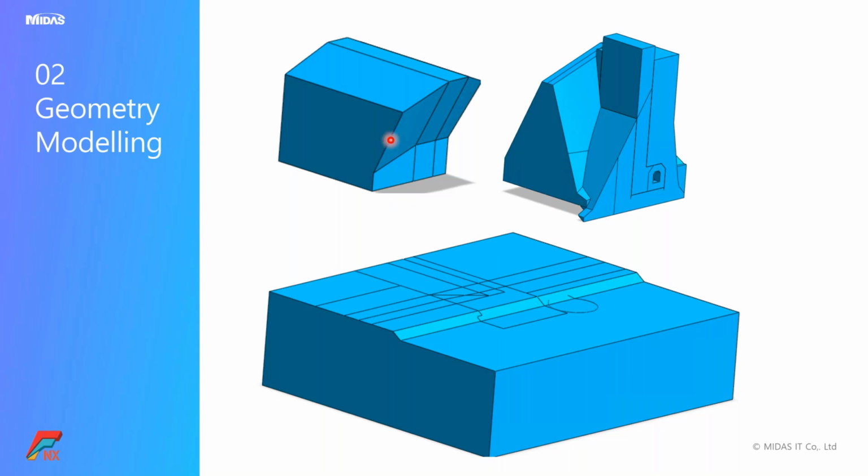Due to this, there will be some additional force applied by the backfill onto the abutment. Hence, we want to consider the backfill as a direct model rather than applying it as a mass or a load onto the abutment. So the idea is to consider the effect of backfill and how it interacts with the abutment due to the earthquake.